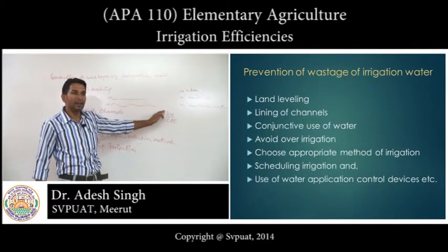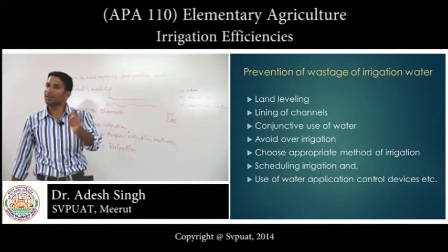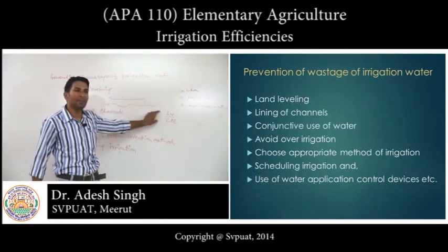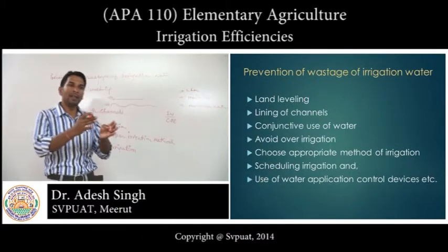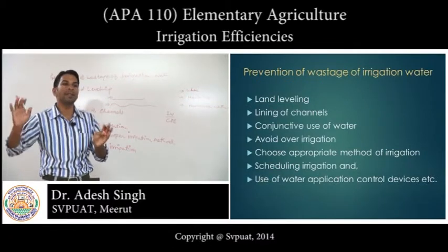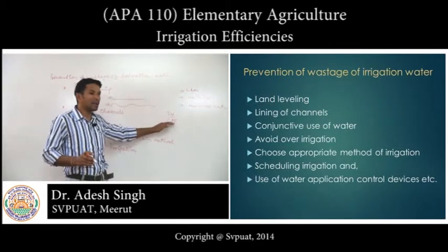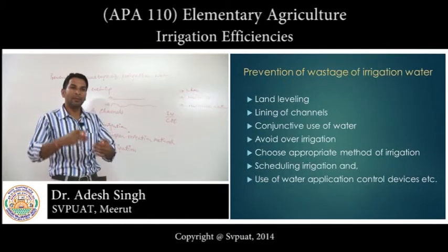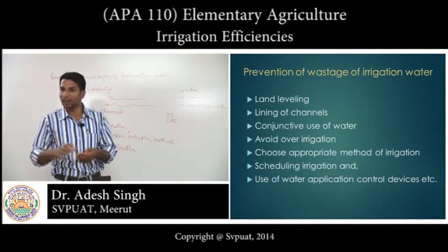Irrigation water, say for example in the surface method, suppose 6 centimeter water is applied to the crop plants, the IW upon CP ratios are fixed for different crops and it will vary between 0.4 to 1.0. 1.0 means the water is frequently applied. Say for example, in case of rice, when the soil is wet, then water is again applied for the next irrigation.